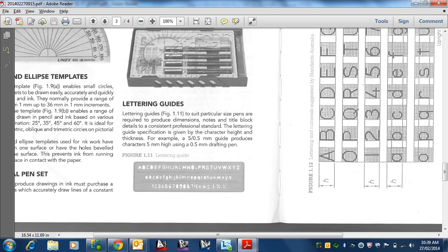They said we're going to have some sort of system to be able to print these things out. So they wanted to visually be able to tell. For example, on your screen, you might have a white shape on there, and it's in white. Well, generally, what they did, they said, well, everything white on my screen shall go to 0.25, because they were used to picking up the white pen to do a 0.25 with, and same with the 0.7, maybe the blue. The yellow, almost certainly in every office, it's been agreed that the yellow shall be 0.35.